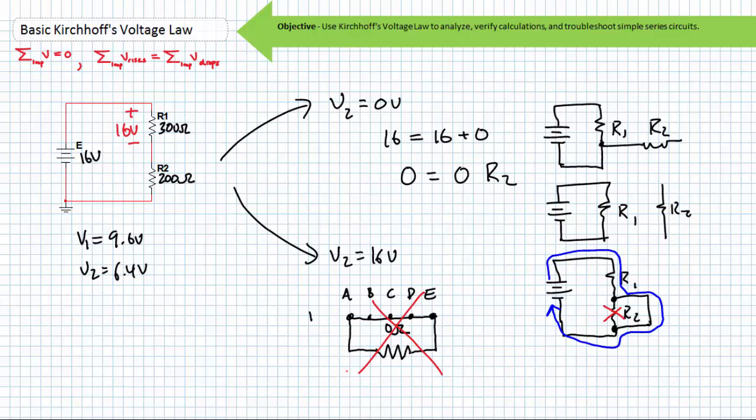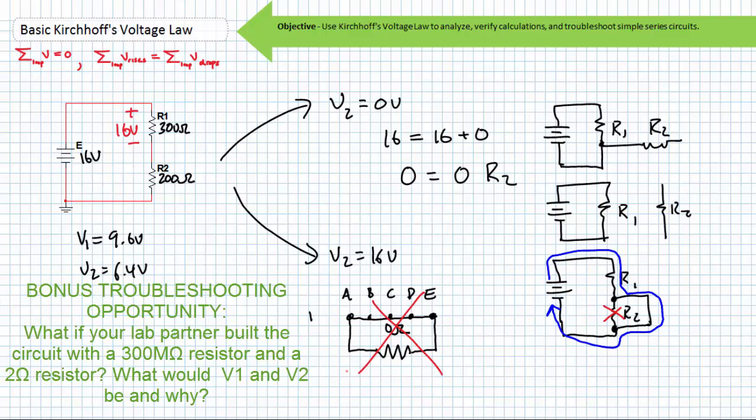Close visual inspection of the as-built circuit will quickly indicate which error is present. Only in sheer desperation would you ever resort to additional instrumentation, such as an ammeter used to measure current through R1 or R2. Again, use your senses to find the error, and only in extreme scenarios would you ever use instrumentation to extend the reach of your senses.